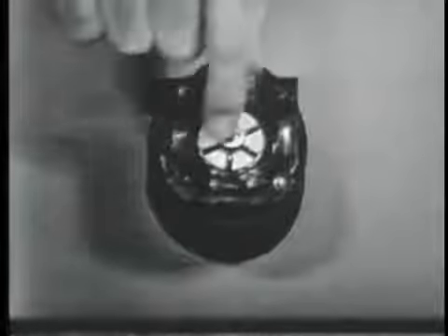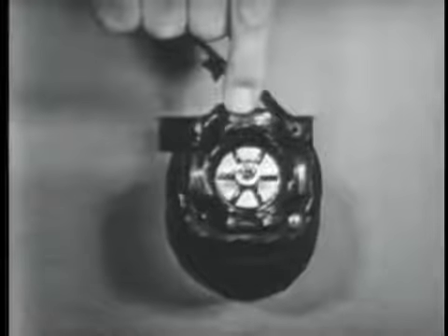In the induction motor, the moving or rotating magnetic field is supplied by the stator field windings. Right. And the rotor follows this field movement because it becomes an electromagnet. In other words, when current is applied properly to these windings, a magnetic field is generated that rotates about the housing. Now, the field windings do not move themselves, and this rotor is not a permanent magnet.